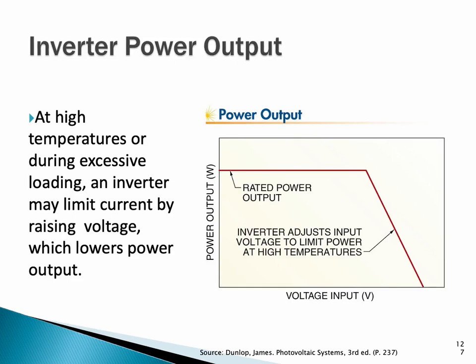I can overload a 7,000 watt inverter to, say, 10,000 watts safely without damaging the equipment or being inefficient with the use of the array. There are calculations that we can do by hand, or we can enter them into a program, and it tells us what is the optimal string size to go into a particular inverter. We're looking at the voltages, and then we're looking at the ultimate watt output.